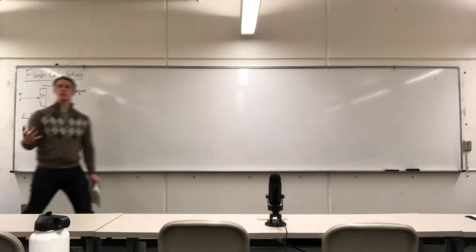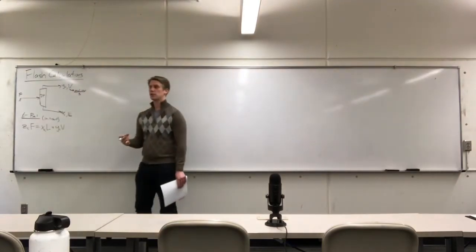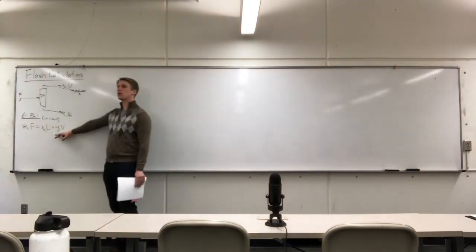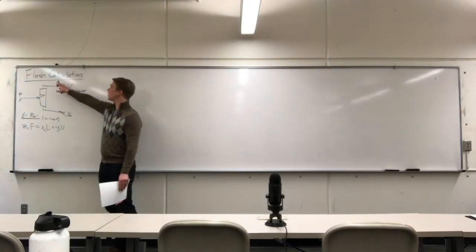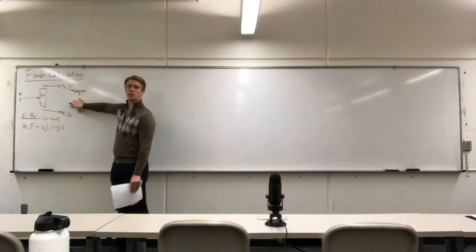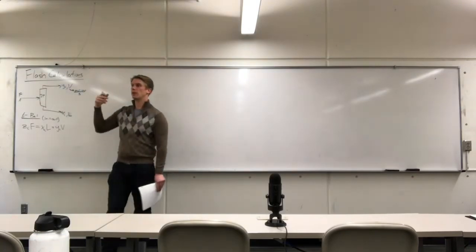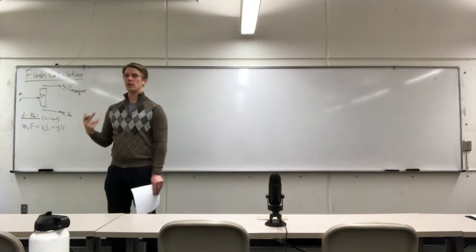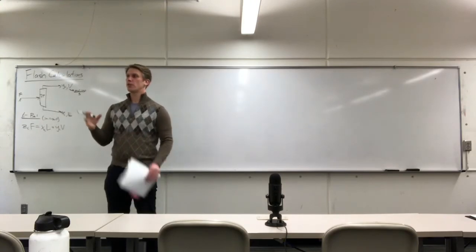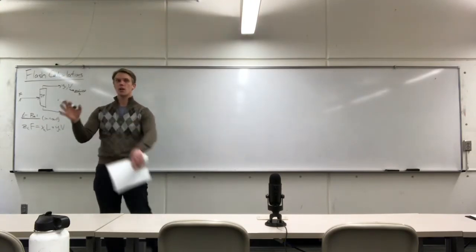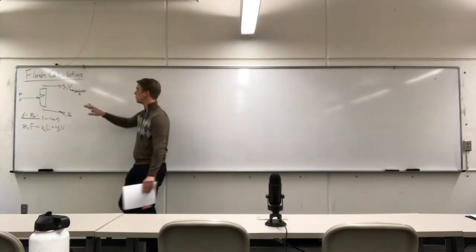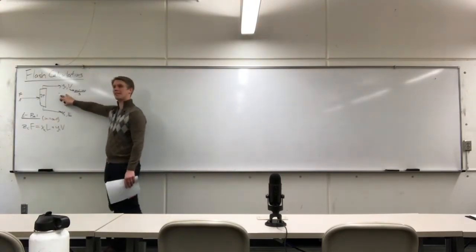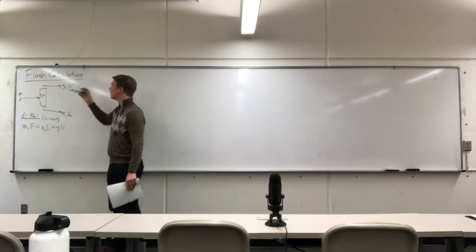So this is what conventionally we refer to when we talk about a flash drum, because a majority of what we'll do as chemical engineers is vapor-liquid transitions. But generally, a flash calculation is any phase equilibrium calculation where you determine the compositions and quantities of each of the two phases. So a flash calculation could be solid-liquid, it could be vapor-liquid, it could be liquid-liquid. We typically think of it, though, as chemical engineers as this unit operation.